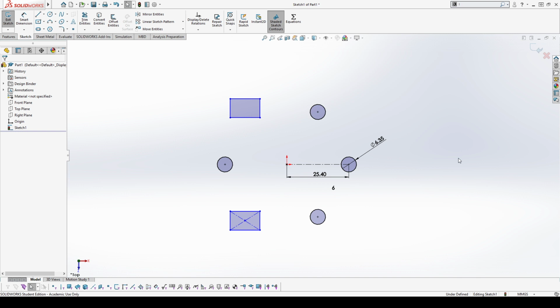That's basically what it does. Out of the stuff that you select, SolidWorks picks out the construction line and it assumes that's your center line that you're trying to mirror things over. So if you think back to when we were creating our lines, and the drop down the center line, again, it's just a simple construction line that it's making, but you can think of it that way. Anytime you're plopping down or selecting a construction line, you're selecting it as a center line for the mirror entity's operation.